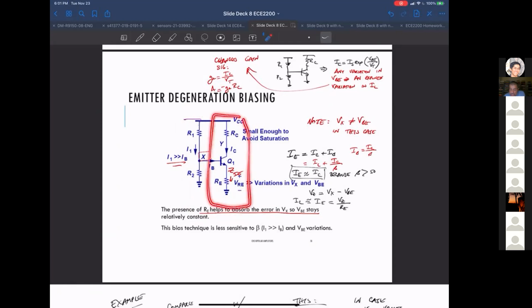You get better linearity. We haven't really talked about linearity much in the class, but that's a pretty big figure of merit for analog design. Imagine anything that's nonlinear gives you distortion. Again, using audio as an example, sometimes maybe you want distortion for some sound effect, but generally it doesn't give you a true reproduction of the sound.